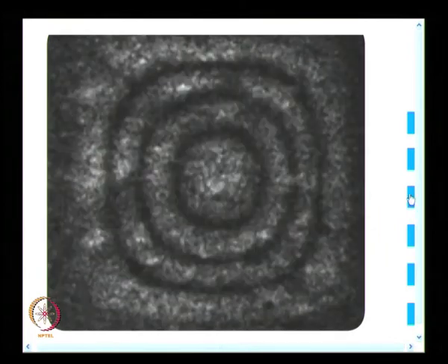and I can change the load here, and you can see the fringes, and the first impression you get is they have very low contrast, and they are not as smooth as what you get in photoelasticity. They have speckle, you will see dots everywhere, a collection of dots.